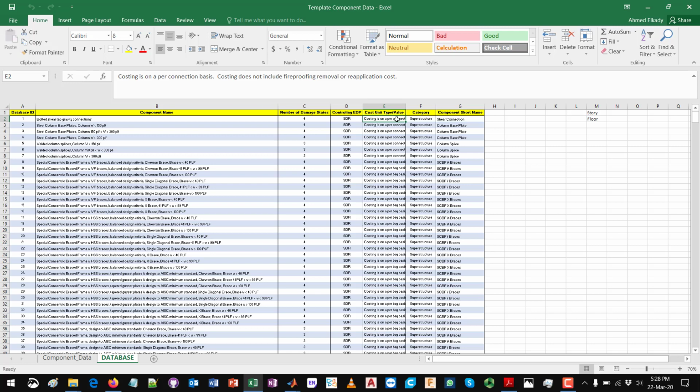So essentially for each one of these components, and this is very important, the parameters of its fragility and damage consequences, for instance the specified values for the repair cost, the associated repair time for a given damage state, and the number of injuries or casualties, everything that's defined for a given component is based on some unit number or quantity of units of this component.